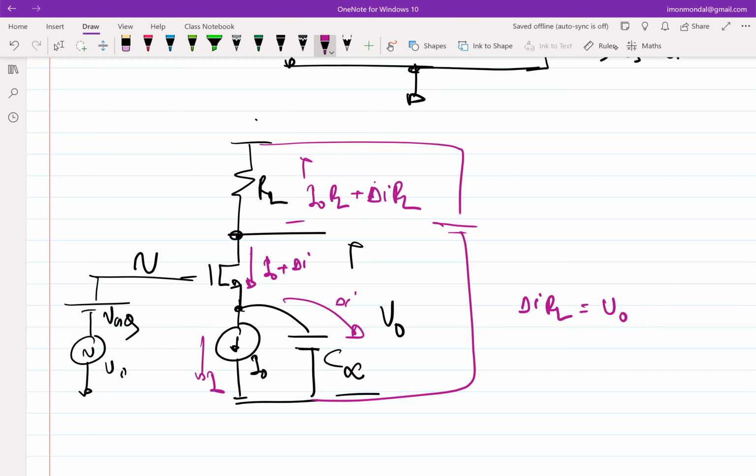The way we bias this configuration, we argued that there is a parasitic capacitance, current goes into the parasitic capacitance, shuts down the transistor. So why is that not happening? Because clearly delta I is flowing into C infinity. If C infinity is large enough, it's like an infinite bucket of charges. A small delta I will not really cause any issue.